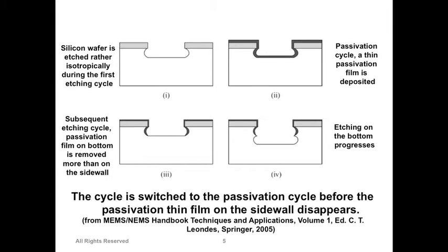So how it works is, you first do etching, some reactive etching, maybe with the ions also, and then you have this structure, right? So you start making this structure, and then the process will start getting slow, and it's also etching on the sides. Then you do a polymer deposition, the second round, a passivation layer, a thin layer of a carbonated polymer.